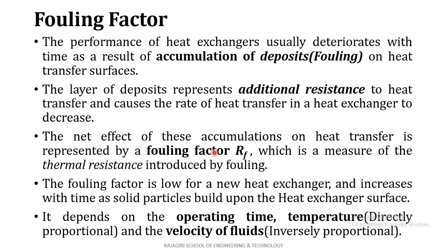The net effect of these accumulations on heat transfer is represented by the fouling factor, which is denoted by Rf. It is a measure of thermal resistance increased by fouling. Obviously for a new heat exchanger, the fouling factor is low, but it will increase with time as solid particles build up on the heat exchanger surface. The fouling factor depends on three factors: operating time, temperature, and velocity of the fluids.